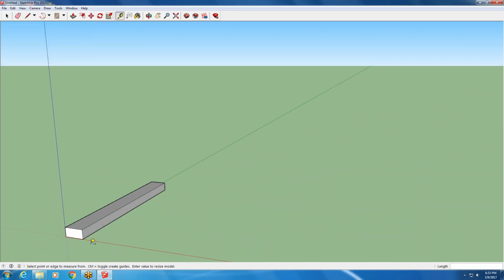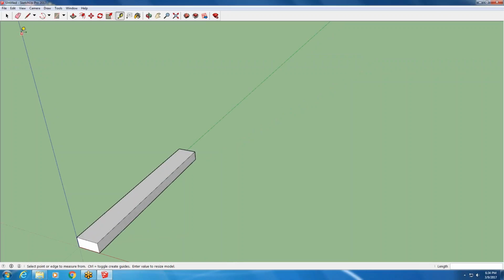So we talked about retracing an edge to close the loop, which will make our face reappear, so I can cross that off of my to-do list. Drawing a line all the way across a face divides it into 2, with the line tool or by drawing a rectangle. So if I draw a line in the middle of here, you have effectively created 2 faces.